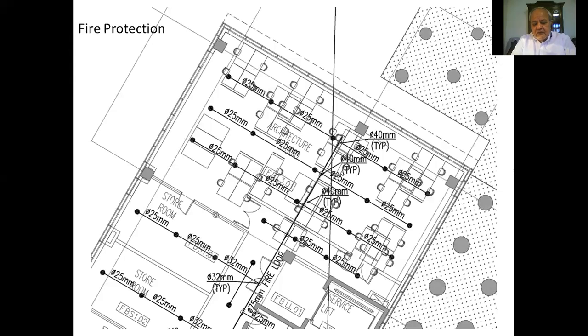You can have a suspended ceiling of gypsum board. You can have acoustical tiles, 60 by 60, and this is the industry standard. We can have a plastered wire mesh, but this is difficult for maintenance later on.